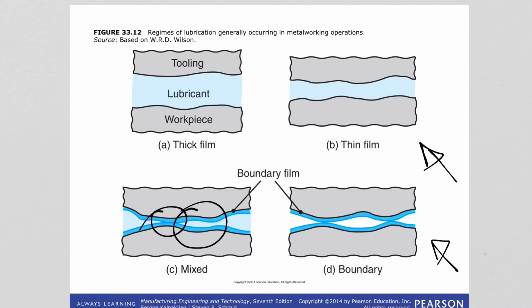And you see the film is attracted to the metal surfaces, preventing direct metal-to-metal contact of the two bodies. This will reduce the wear. You are seeing direct contact is prevented basically due to the formation of this film. Boundary lubricants typically are natural oils, fats, fatty acids, but this film can break down as a result of high temperatures or just being rubbed off during sliding.